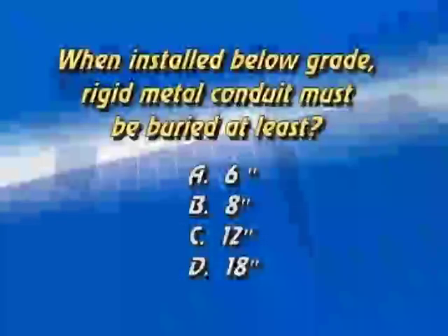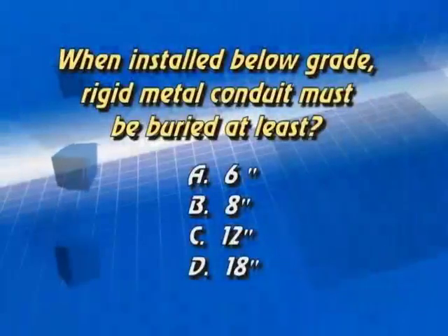Number 10. When installed below grade, rigid metal conduit must be buried at least 6 inches. Letter A.